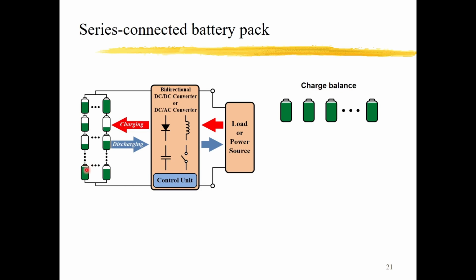So we cannot charge the battery any further because this cell is full. If we keep on charging, this cell is overcharged and might explode. So the charging is limited by the highest SOC cell.